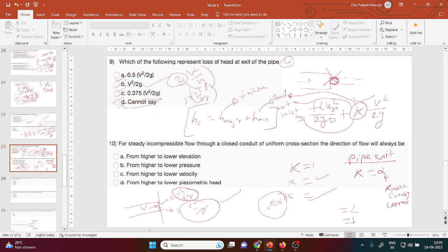In the fully developed region, your velocity diagram is similar throughout the channel, unlike the core zone before it. Because shear stress and pressure are related with the velocity, we always focus on finding the velocity in fluid flow.